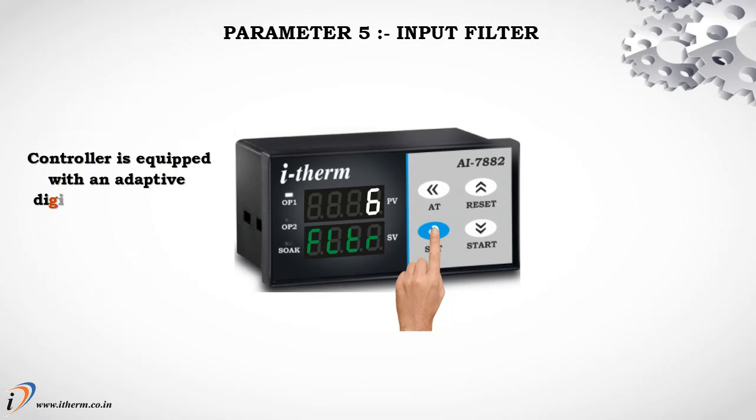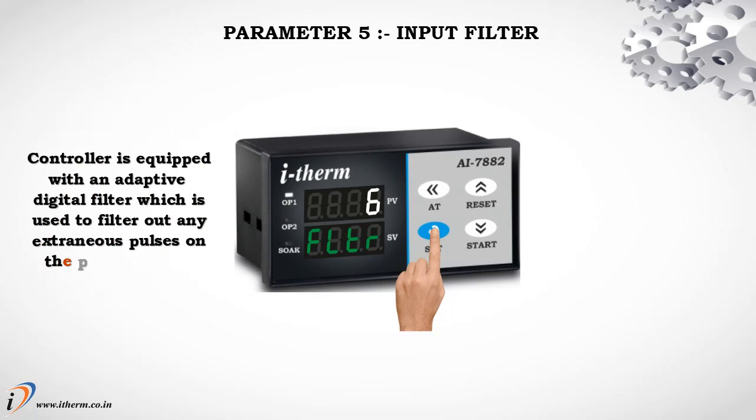Parameter 5, Input filter. The controller is equipped with an adaptive digital filter which is used to filter out any extraneous pulses on the process value. The default input filter value is 6.